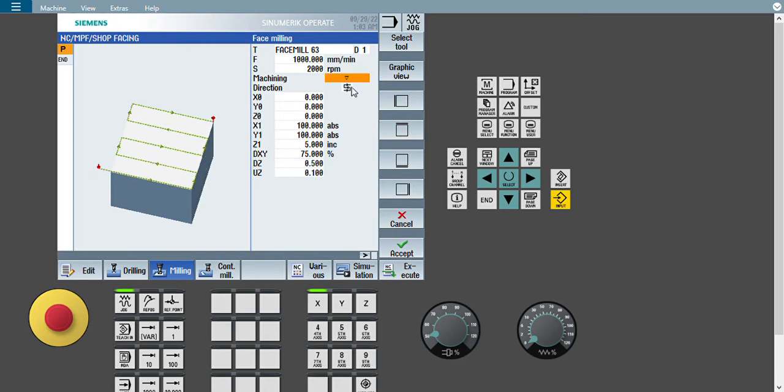If you want to cut a high amount of material, let's say 10 mm material you want to remove from your face, then you have to put roughing, meaning the first one triangle. If you place three triangles, the depth of cut option will disappear. You will not see the depth of cut option. See, DZ is the depth of cut, so the option is appearing. If I select finishing, this option will not appear. So I will select depth of cut.